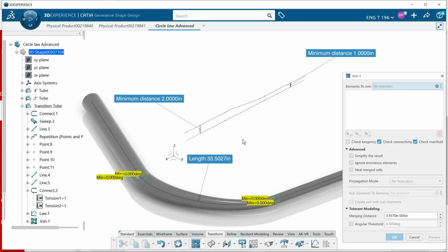Thanks, Chandler. If I go to join, your definition curve on the top should be the same length horizontally as the reference curve. In other words, this end should project straight up and hit the end here, and this end should project and hit this end here. That wasn't the case when I didn't join it, right? Now I have this curve a third over, transitioning down, and then a third over. Select OK.